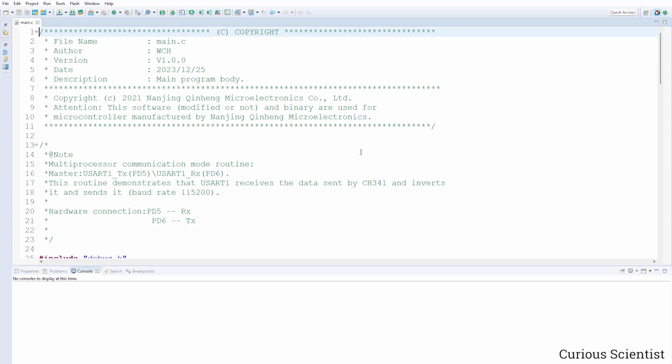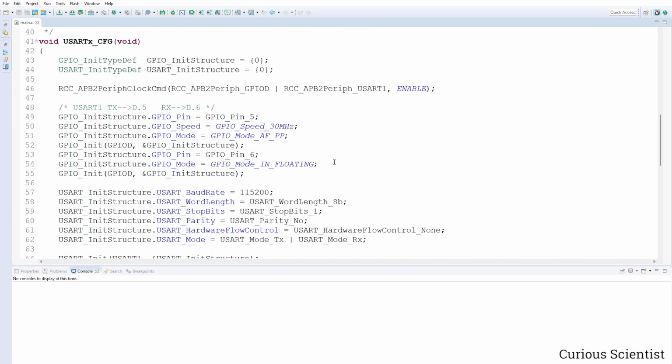As I mentioned in the beginning of the video, the example code already has the USART code implemented, so we will base our tutorial on this already existing code. Just as a reminder, we are using USART because the chip doesn't have any native USB. So we need a USB to USART converter, and that is actually the programmer. The programmer has this function that can convert the RX and TX pins into USB communication, and then we can communicate back and forth with the microcontroller through the programmer.